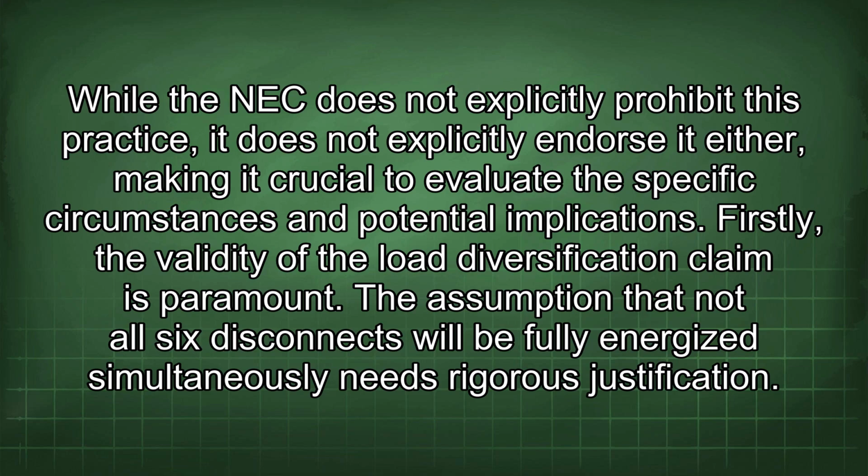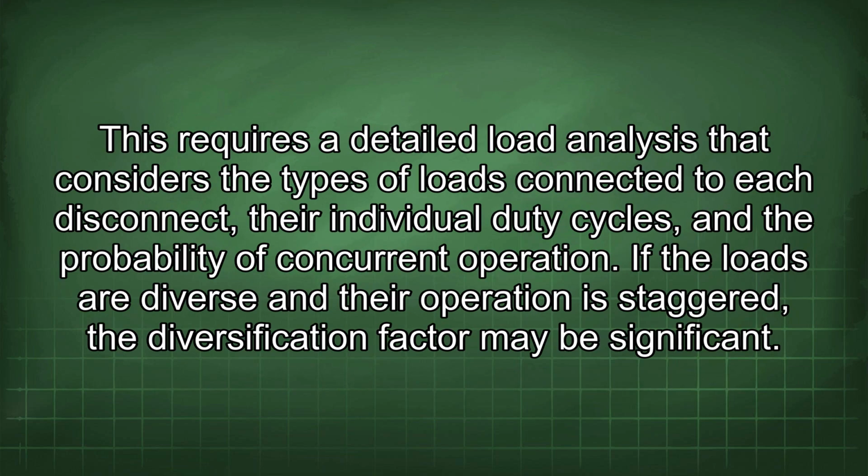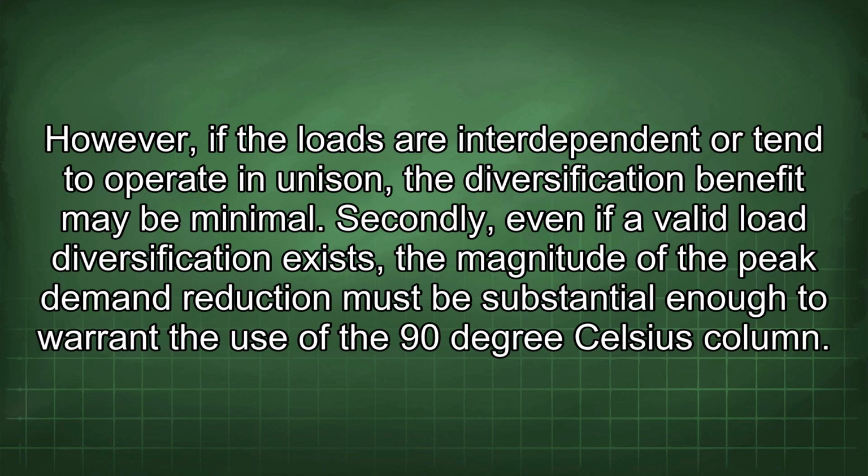The assumption that not all 6 disconnects will be fully energized simultaneously needs rigorous justification. This requires a detailed load analysis that considers the types of loads connected to each disconnect, their individual duty cycles, and the probability of concurrent operation. If the loads are diverse and their operation is staggered, the diversification factor may be significant. However, if the loads are interdependent or tend to operate in unison, the diversification benefit may be minimal.